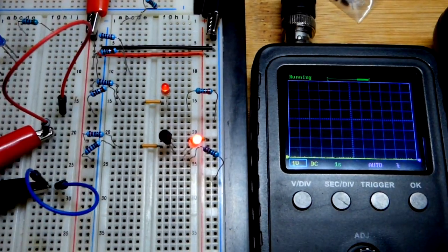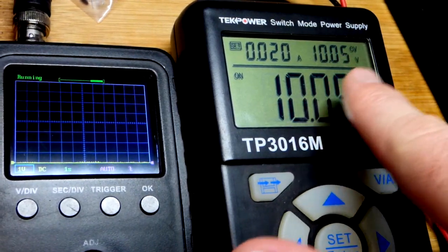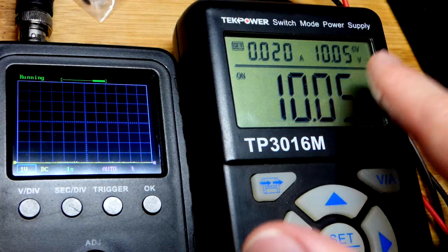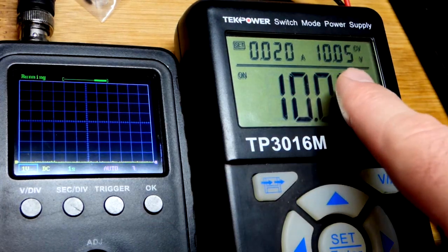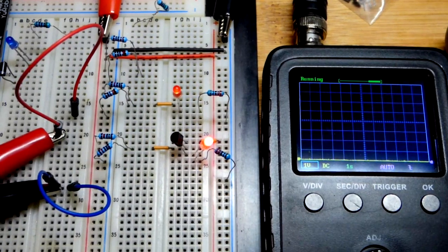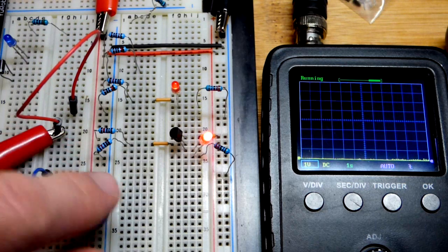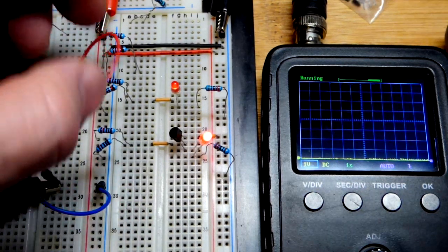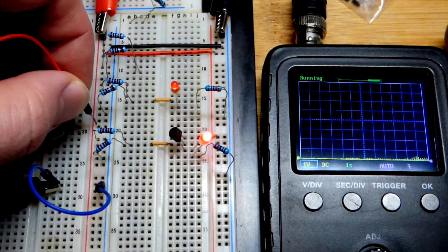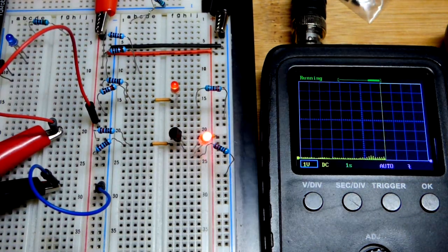And we will zoom back and look at those voltages. So I have the oscilloscope there, my power oscilloscope. I have the power supply set to just a speck above 10 volts because a little bit of voltage gets lost along the way. So that'll help get it to 10. I only have 8 squares, so we can't really use this oscilloscope to look at the supply voltage. Our voltages are all going to be in relationship to ground. If we look at the supply voltage, it goes off the screen right there, all the way up. So let's, there we go, much better.